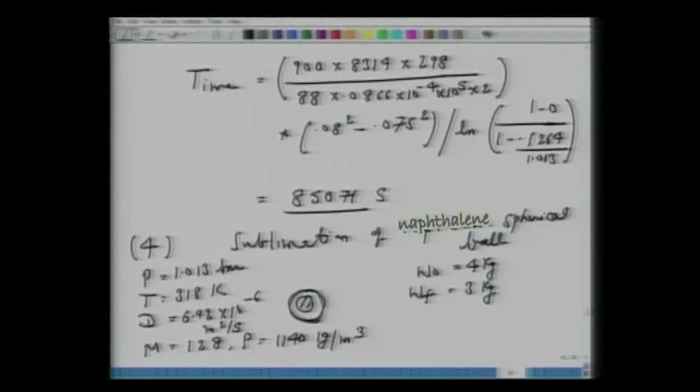Okay. So now look at the evaporation of this naphthalene. So when it diffuses, first it has to evaporate. So it evaporates into atmosphere, which is air. So if it evaporates, then there has to be a concentration gradient. So all it means here, the concentration at the surface is controlled by the vapor pressure, or what we call sublimation pressure. It's a solid, so the vapor pressure or sublimation pressure is dependent upon temperature.